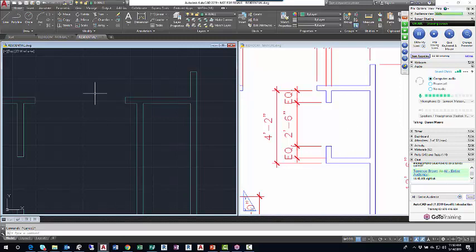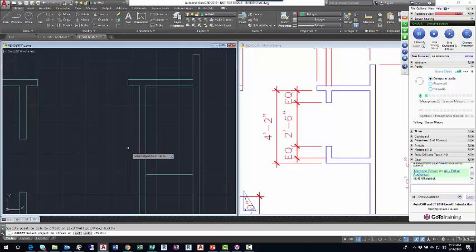So that's a change. So I'll go offset 4 feet 2. Enter. I'll left click this line, move down and left click. So there's the bottom edge of that closet, if you will. All my walls are 3.5, so I'll offset this line up 3.5. Offset 3.5. Enter. Left click and I'll go up. I'll exaggerate. I'm going way further than I need to. Left click. Because sometimes if your object snap catches you, it shoots you so fast you can't see the difference. You can't see the change that happened.